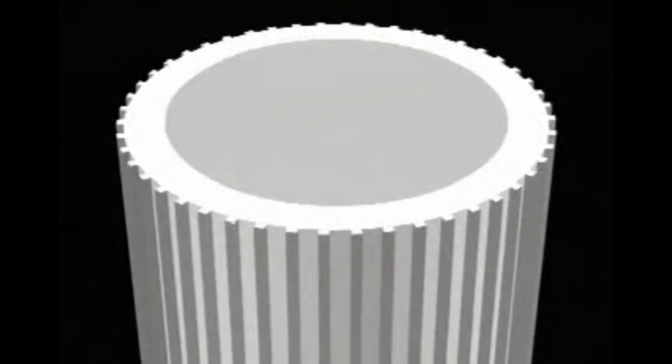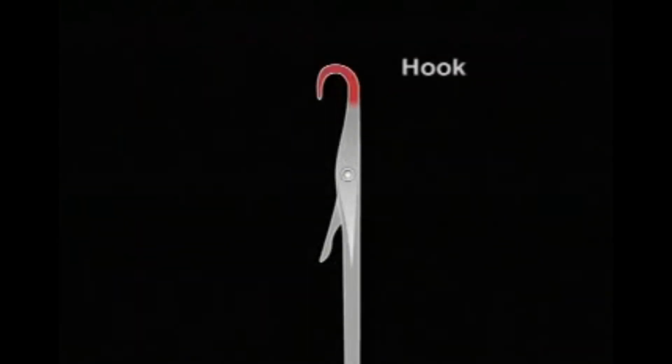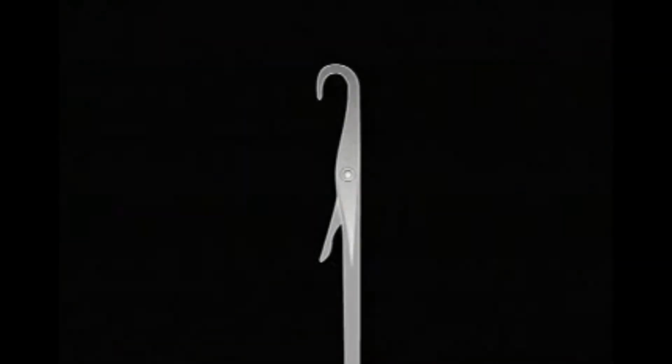The total number of cuts around the circumference of the cylinder would indicate the number of needles in the cylinder. The more needles, the wider the fabric. Now let's take a closer look at the needle itself and label its parts. At the top of each needle is a hook. Below this is a latch, attached with a rivet. Notice that the bottom edge, or cup of the latch, is curved to fit over and completely close the hook.